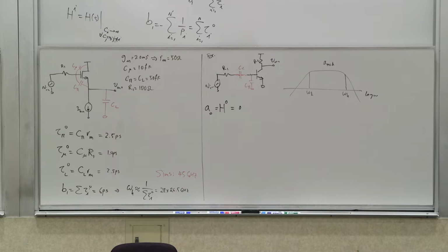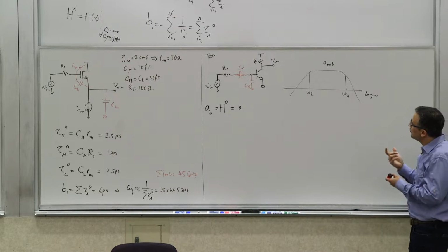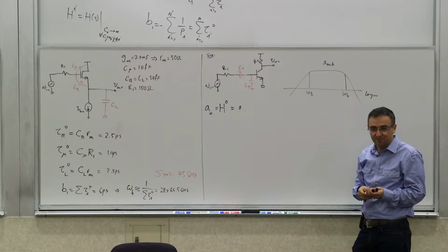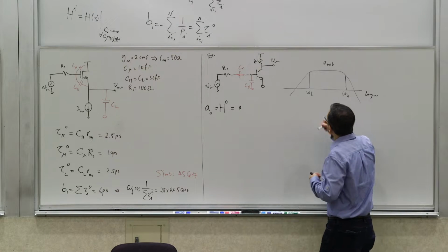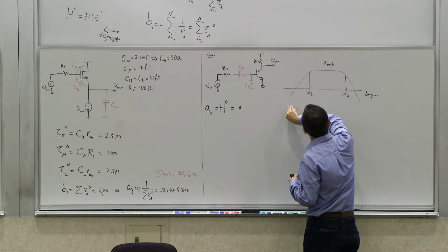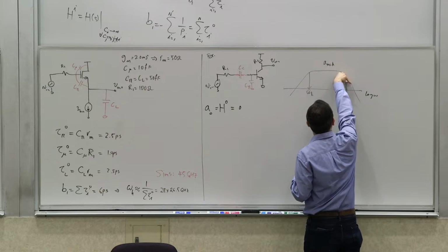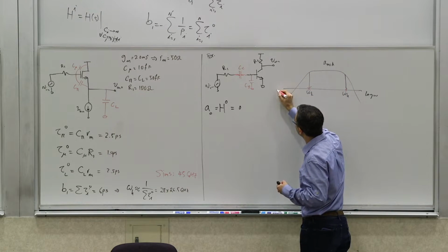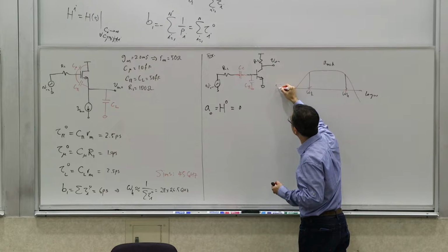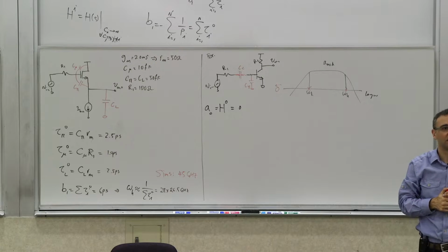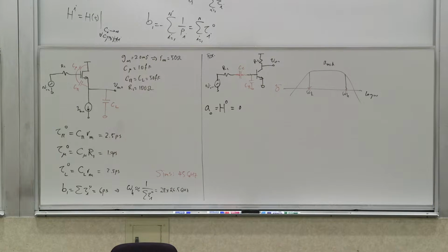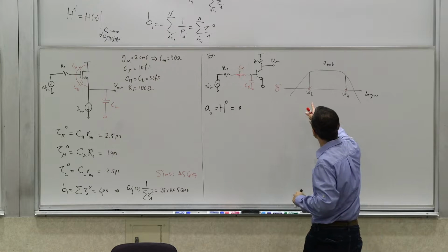And we said this has 2 poles and a 0. And the left half plane 0. So where is the 0? Where are the 2 poles, first of all? What frequencies are they at? Omega L and omega H in this case, right? In this case, they happen there. Because this is, you started up going up, just it made it flat and it made it drop. So the 0 must be at negative infinity, or basically at 0 frequency. So there's a 0 at the origin. That makes it go up, and then at omega L you hit it.